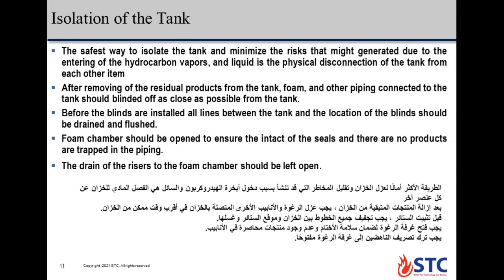The safest way to isolate the tank and minimize the risk that may be generated due to the entering of the hydrocarbon vapor and liquid is the physical disconnection of the tank from each other item.